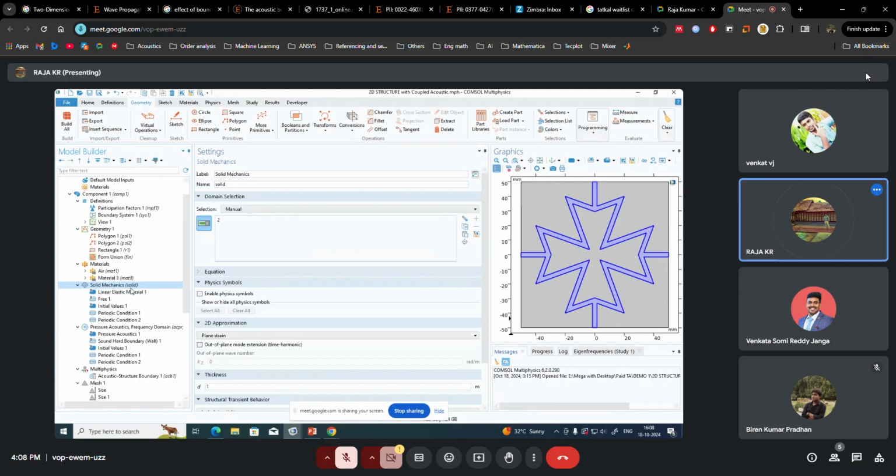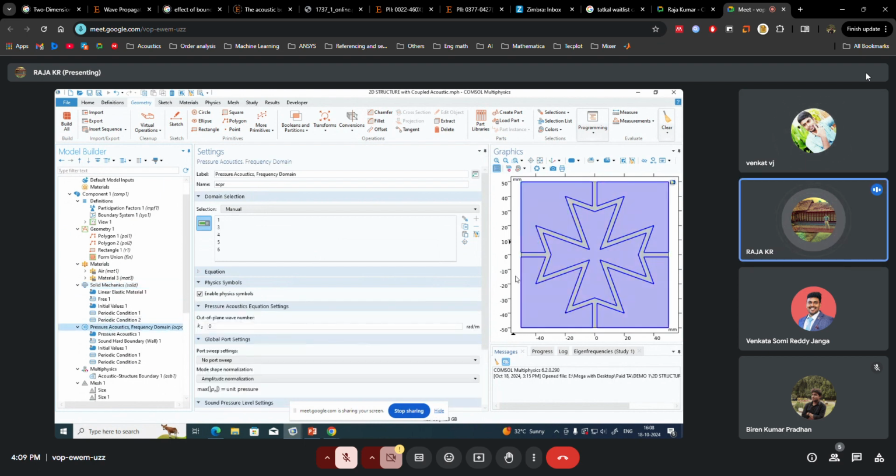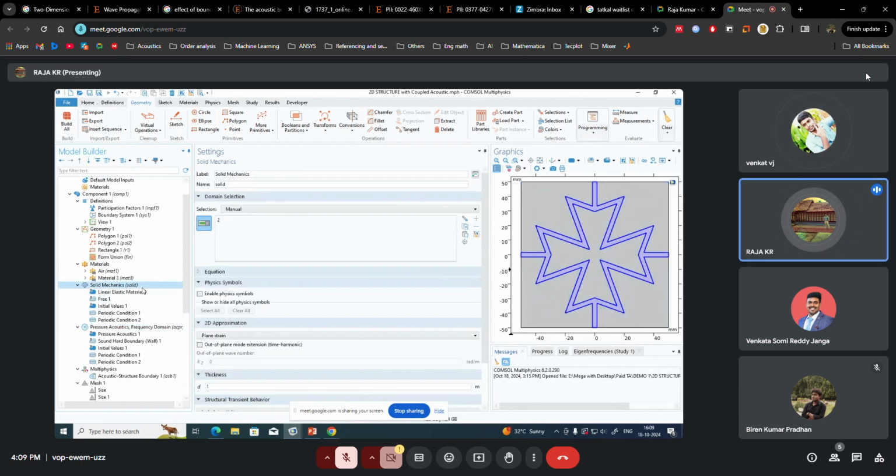Now, this is your solid mechanics domain, and this is your pressure acoustic domain. How do we define it? I will show you. This is your geometry. Just select the domain. There is domain selection, where you can select manually. Just click it here; you can select anything.